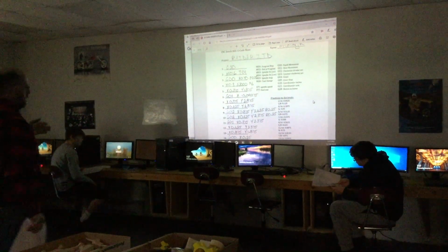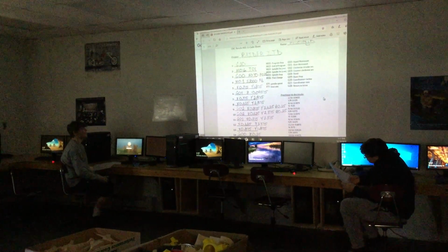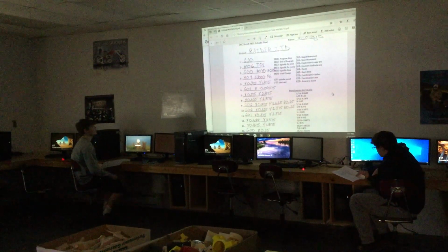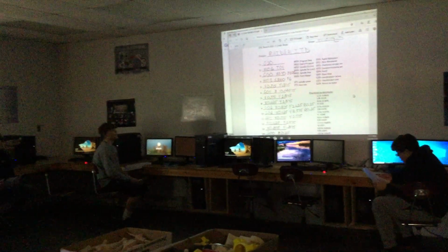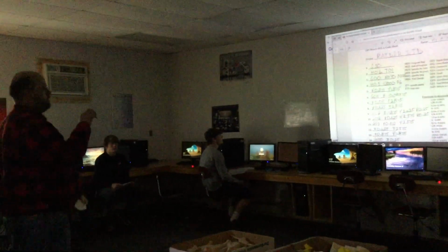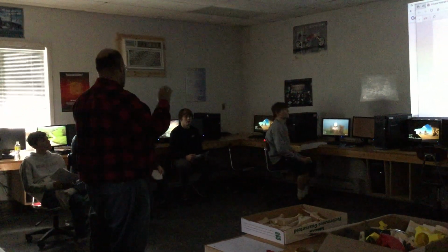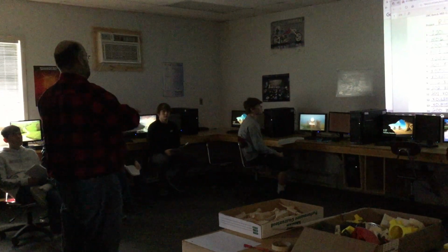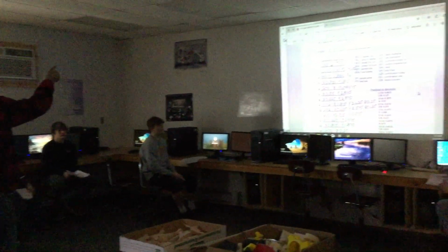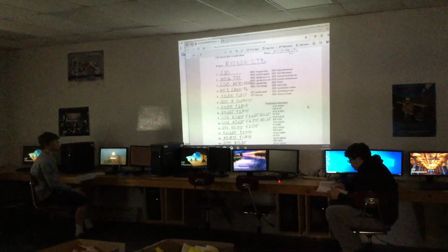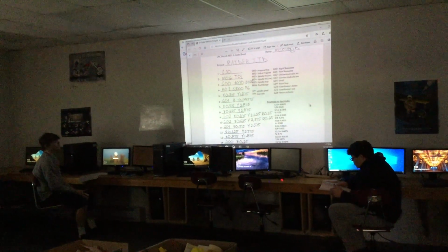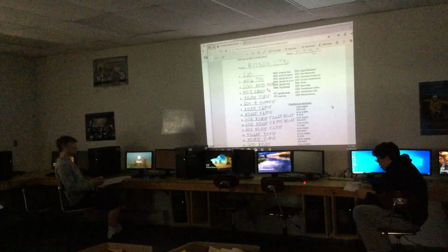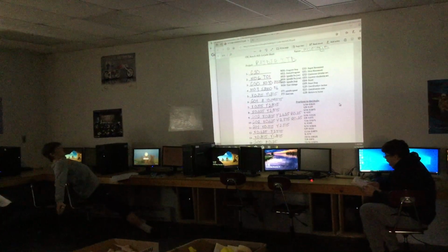What is the decimal of a 16th, the decimal of an 8th? A lot of that just comes to memory for me because I had to learn all that in college, and I still use it now when I'm using AutoCAD to draw 2D stuff. You use decimals a lot when you're putting in measurements. It's the same thing here, but I put it there so you can refer back to it. So we go to that X 3/8, you go left to right, and then we go up an inch and 7/8 according to this graph. And then step 6, what am I doing?